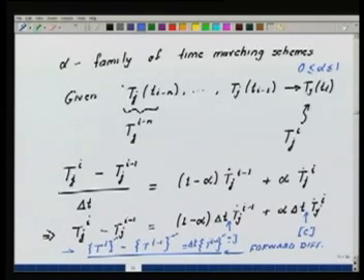What happens is, if my time step, this delta t that we have chosen, is bigger than a critical time step size for the representation that we have taken, the discrete representation, that is for the choice of the degrees of freedom n or the choice of the mesh, then my temporal solution, when I do the time marching, will diverge, it will blow away.